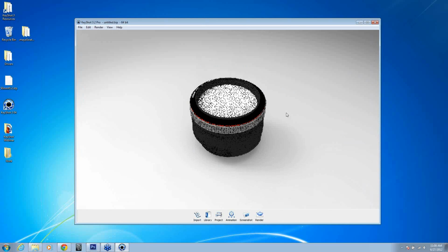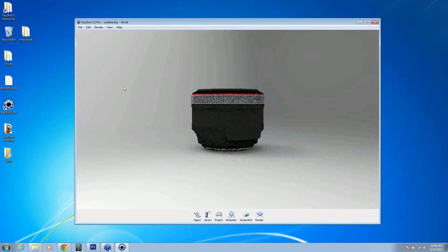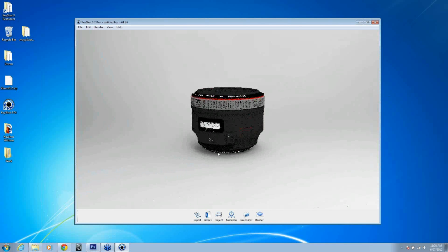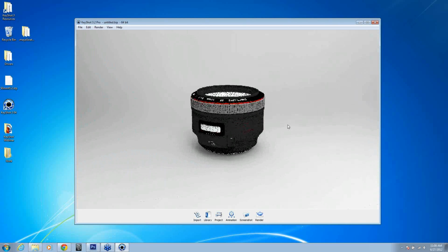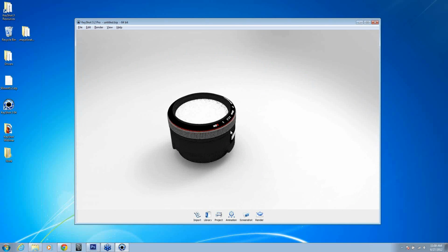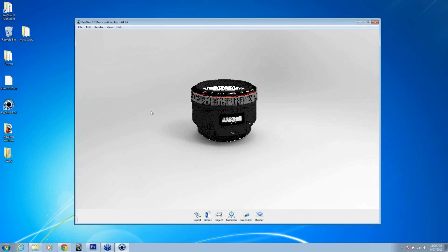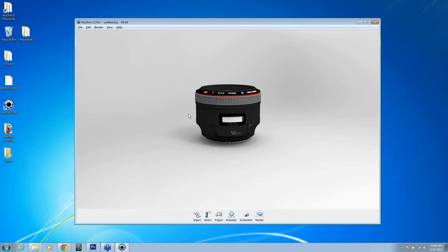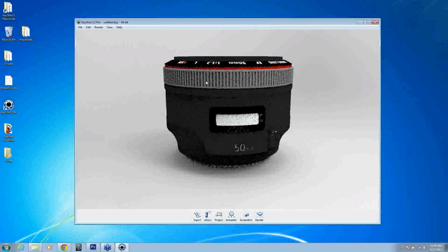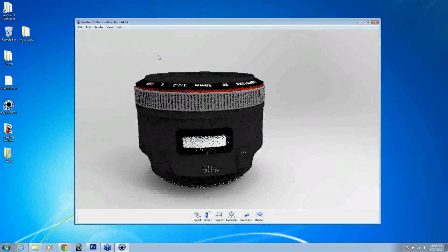And the next thing you need to know is how to navigate your scene. So if you left-click in the scene, this will orbit your camera around, and your camera is always centered around a certain orbit point. And one thing that you can do to control your orbit point, which is a huge help, is press Control-Alt, and if you right-click on an area, it's going to center your camera around that orbit point. So if I wanted to orbit around this little frame here, I could do so. If you want to zoom in, you can hold Alt, and you right mouse, and you move in and out. Okay? If you want to pan your camera, you can hold down the middle mouse wheel, and you move your camera around.